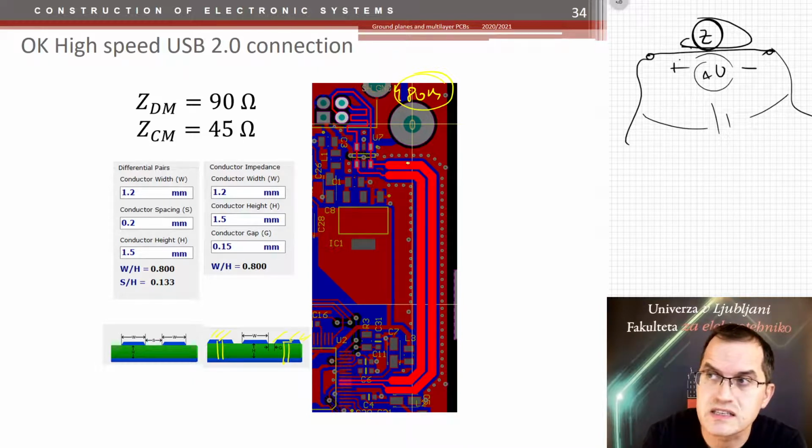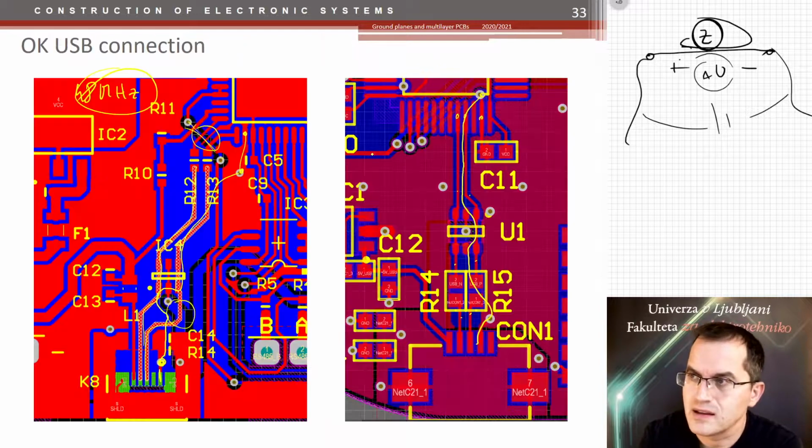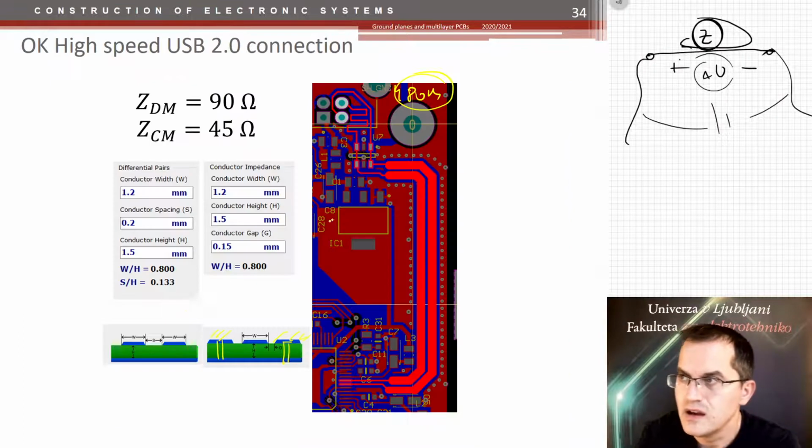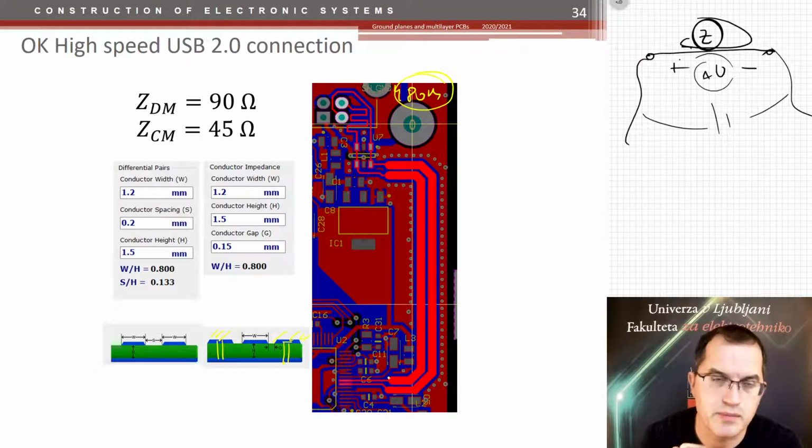But it works electrically. When we did it like that, it didn't work because the impedances were not correct, the lengths were not matched. And here, most of the tracks have the right impedances. And at such high frequency, this is important.